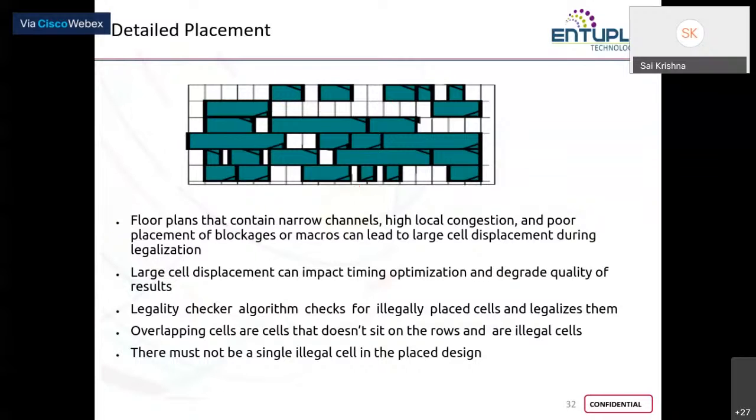Normally, depending on the EDA toolset that you're using, there is a limit within which even if you have congestion, it's okay. For Cadence EDA tools, your congestion level should be less than 1%.